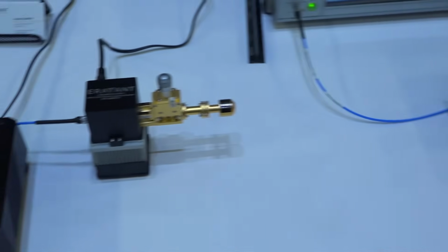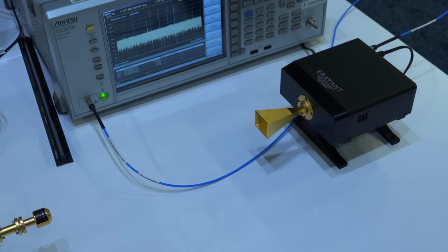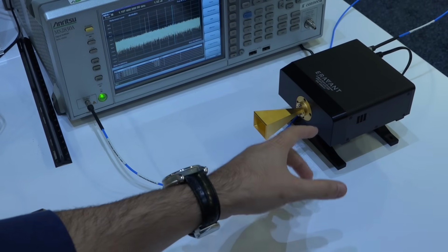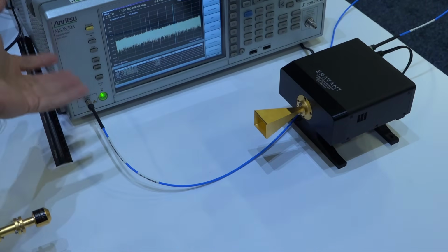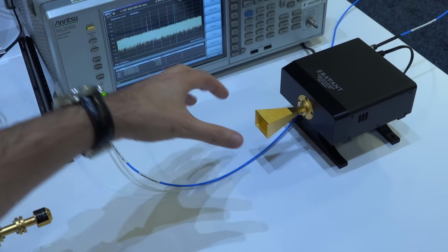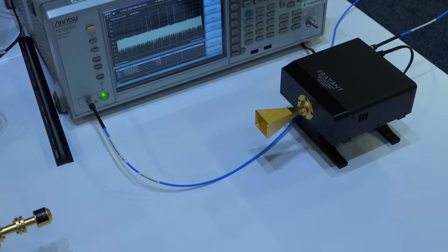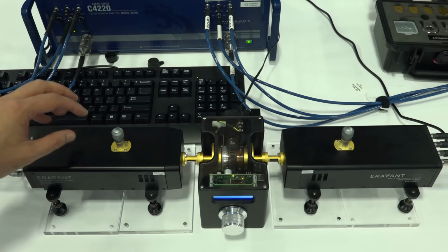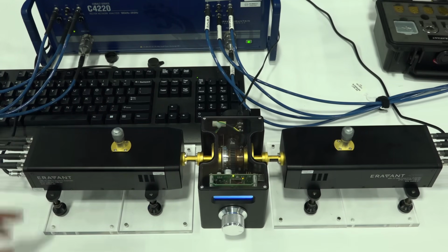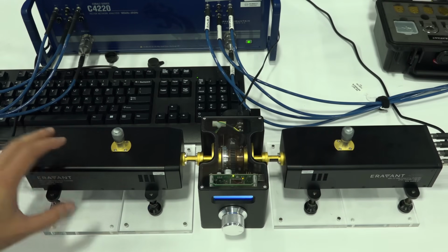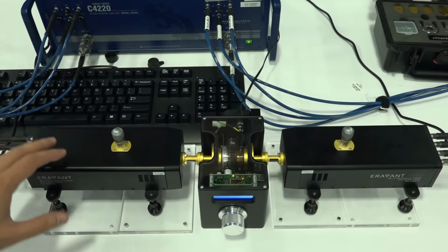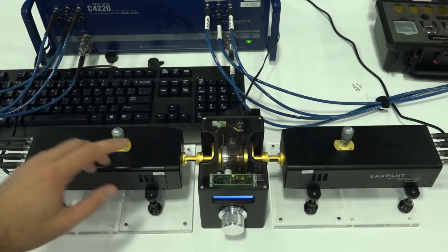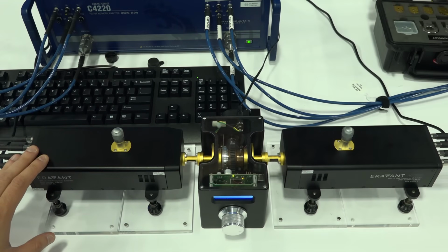On the other side now, they have also upgraded some of their detectors. So this particular one here now has a diplexer built in, so it can connect to things like Anritsu directly from there. And yeah, they're transmitting something across. So here we have the second generation of E-band remote heads from Eravant. These guys actually extend the frequency range a little bit beyond the typical W-band frequency range, so from 67 to 116 gigahertz in the same WR10 waveguide interface.